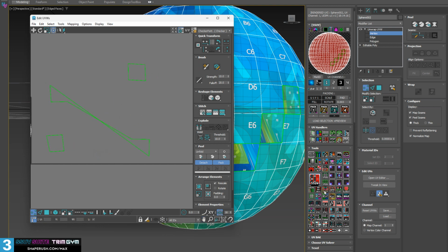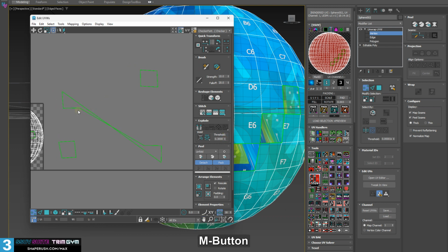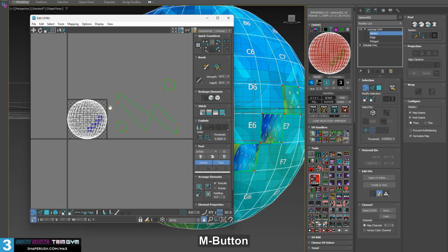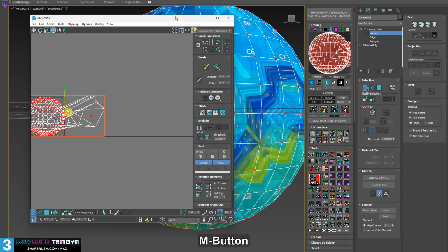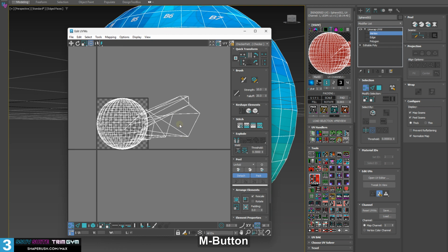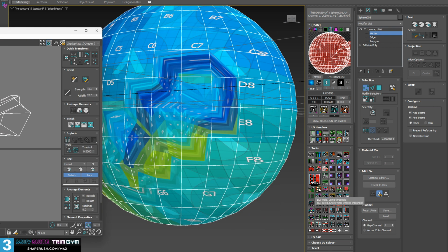Now that's basically what the right click does. So you can leave this threshold in place to always be whatever threshold you prefer, so that when you left click, the threshold will be taken into account. Now, if you just want things that are connected to be welded, we can just select vertices and right click, and that will force a weld at the midpoints of these vertices locations. And now that's a blob object right there. There's no map seams on that. So left click to weld within threshold, right click to force weld it from wherever it is located. All right.